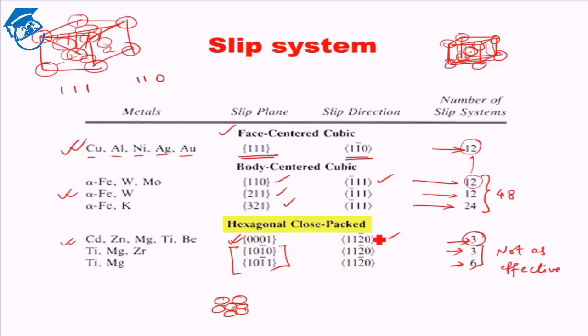I'll not go into the details of the idea which I'm about to tell next, but if you study the fundamentals of geometry, then you'll know that for slip to happen, for dislocation motion, for deformation to happen, this comes from the very fundamentals of geometry and from stress strain relations, that we need a minimum of 5 slip systems for effective deformation to take place.